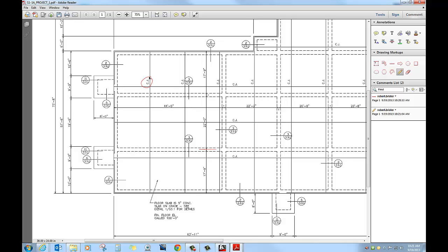But the control joints will be a lighter line than the rest of them, so even though they're on here and there's a bunch of them, they won't really stand out that much. Okay, this drawing that you're looking at actually is not very well drawn, because all the lines look kind of the same thickness, and that's not good. You can see because of that, they kind of start bleeding together and you get lost in it. But we're going to do a better job of creating differences in the line thicknesses.